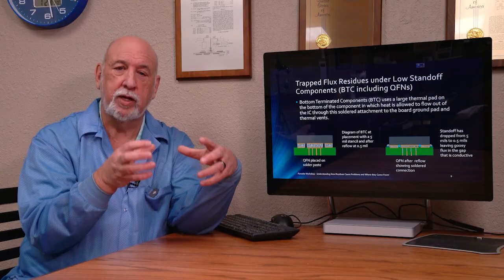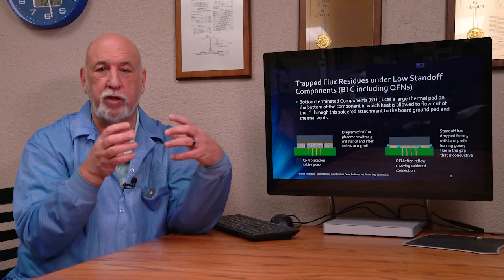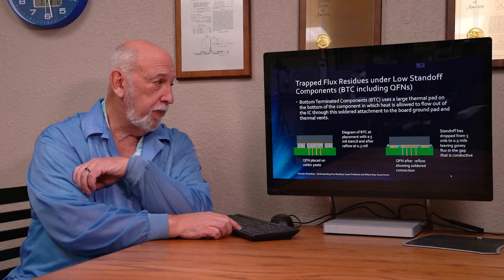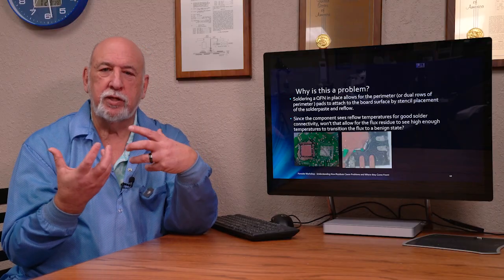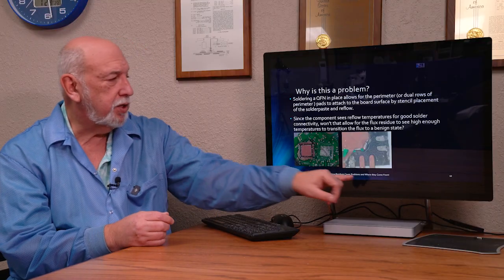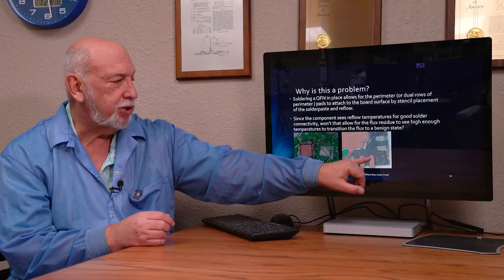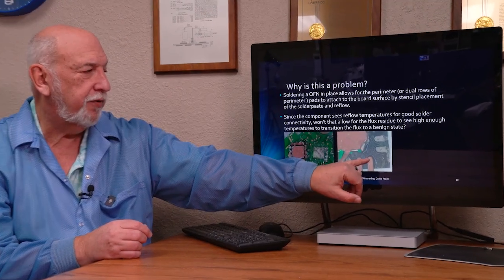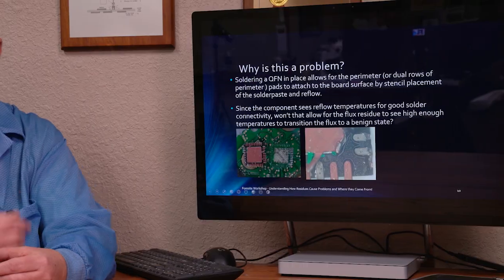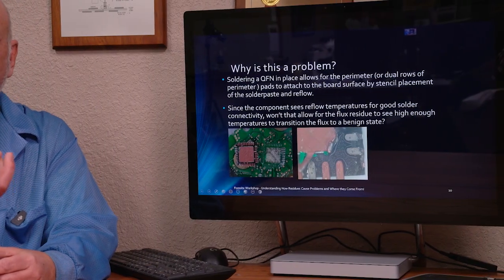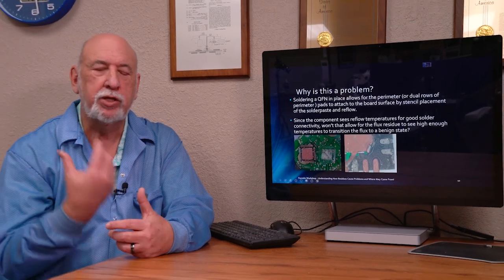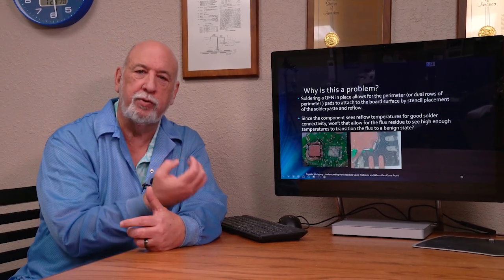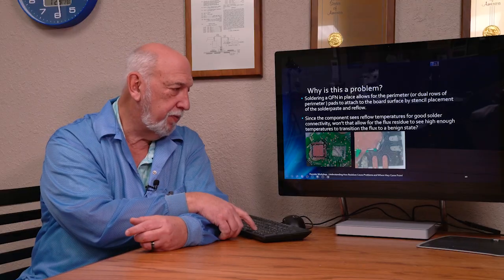And in some cases, if the moisture is high enough and the contamination is great enough, you can get a dendrite to form there as well. One of the other things that gooey flux leaves us is the ability to bridge not just pin to pin, but from the power pin to the ground plane. We can actually see the measured effect between that incoming pin or the output pin to the ground plane if there's a glob of gooey flux underneath that part.